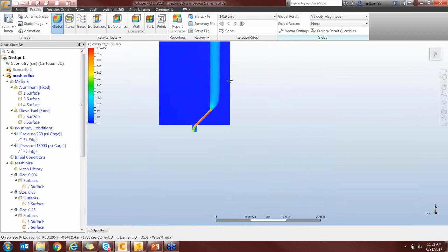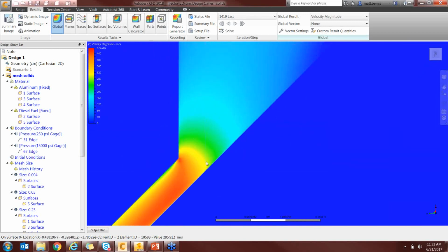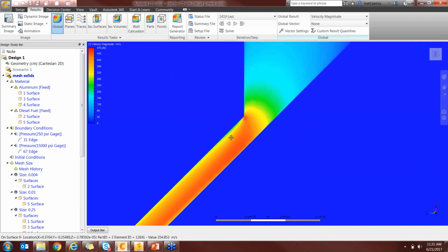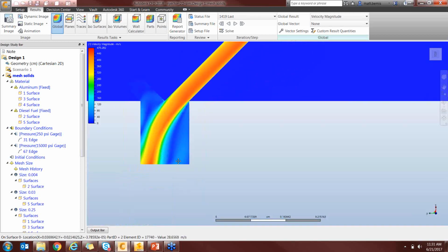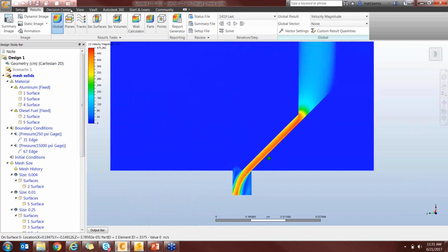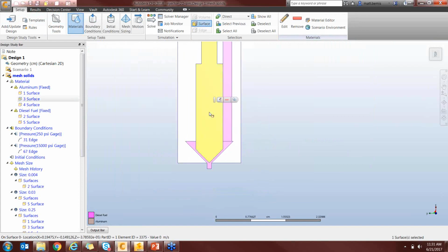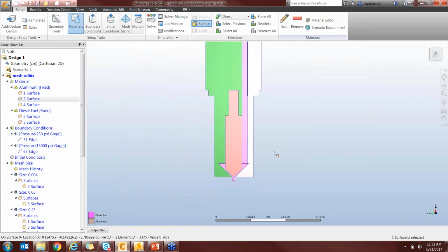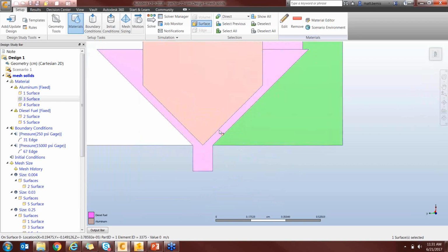Go down to the bottom. This increase in pressure at the restriction, the smaller pipe area, shows nice gradients, as well as this outlet here. So if we just go to setup, basically this would be my needle that's lifted up and down, by the solenoid, of course, and there's my leakage path, I guess.